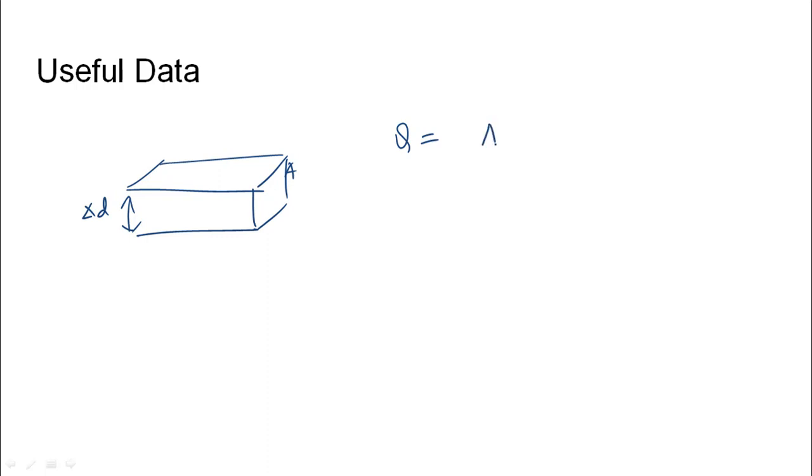When we talk about an aquifer, assuming an area of A and the change in depth of water as delta D, the total change of volume that is expected is A into delta D. But this does not happen because the soil of the aquifer does not yield water at the full volume. There is a small factor associated. That factor is called the specific yield.